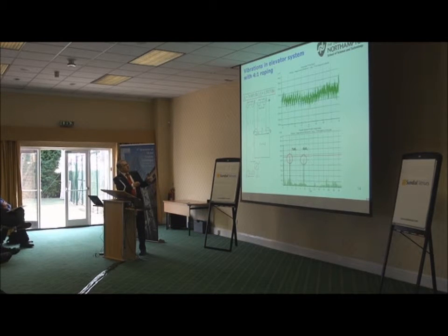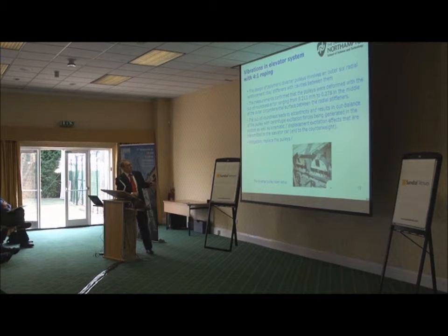This frequency here is responsible for another problem. And what eventually was found was that the pulleys were deformed. They were deformed between reinforcements. And the deformation, the out of roundness error, was quite substantial, from 0.211 millimeters to about 0.3 millimeters. What did it cause? It caused out of balance excitation, and it was periodic. And there are some additional acceleration forces involved. And this caused excitation and resonance.